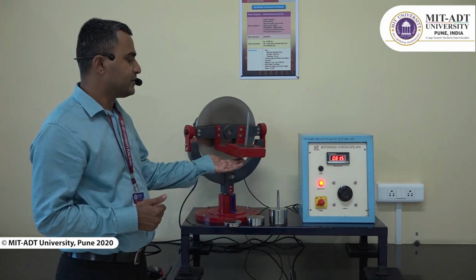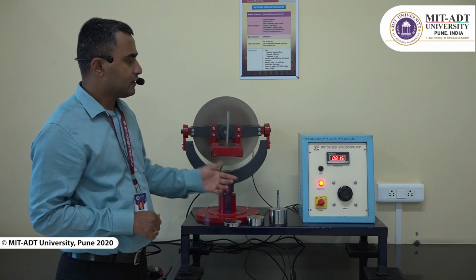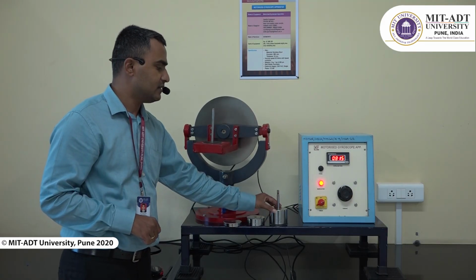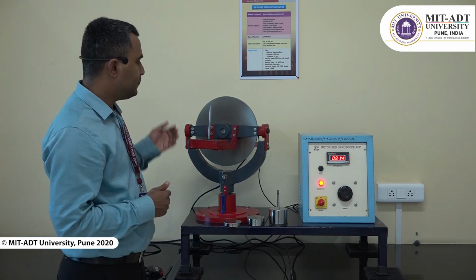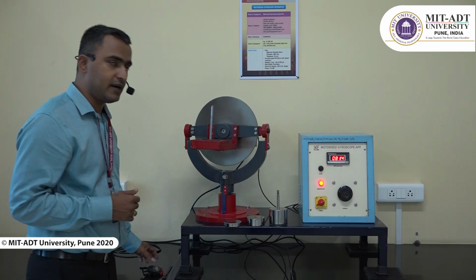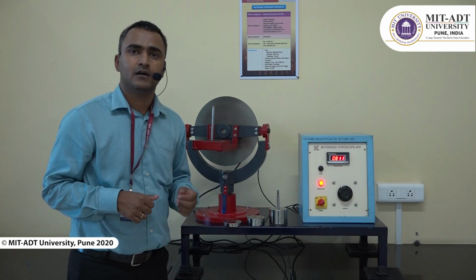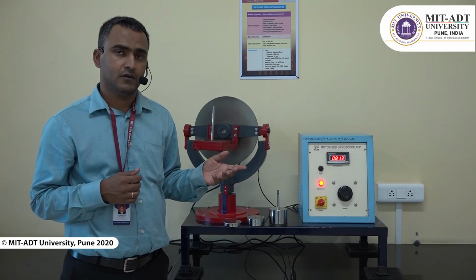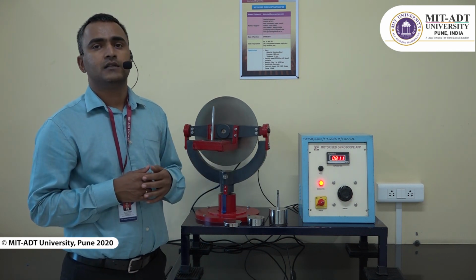So these are the three sub-cases which we can make use of under case number 2 with constant speed and mass variation. The first mass half kg, second mass 1 kg, and the third sub-case would be for 2 kg. This is how we can repeat the steps, measure the time required in every case, calculate the measured gyroscopic torque and compare it with the applied torque to find the percentage error. Theoretically, the percentage error should be 0, whereas practically we may get some value, but that value should be close to 0. That is the case.